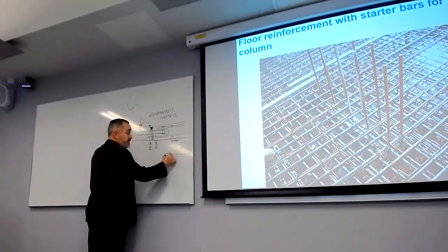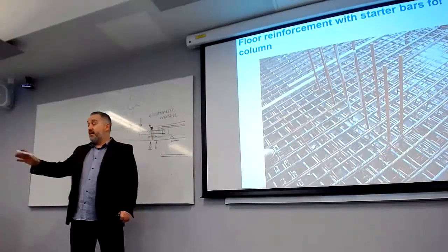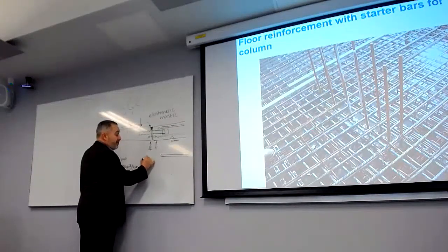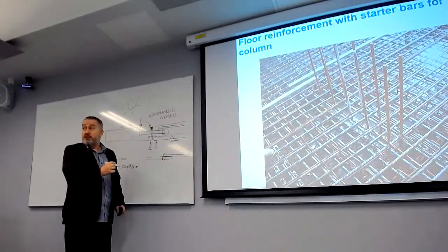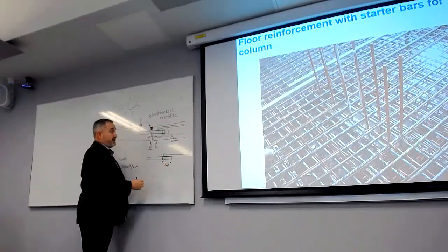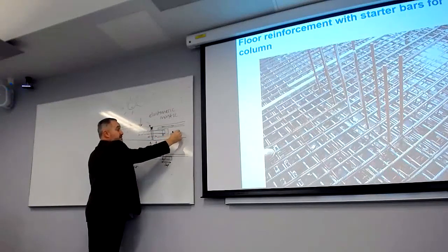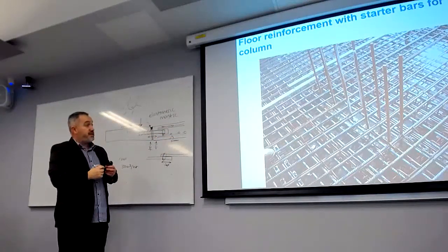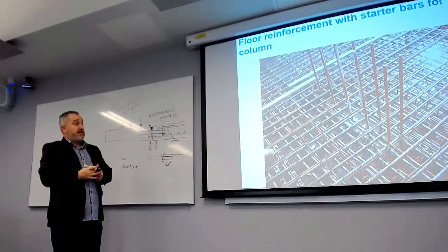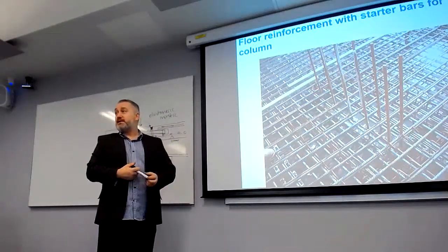you've got a steel bar, but your steel bars aren't the full length. So what you have to do is lap them together, and then you have to tie them. And then you've got rules about how far you should lap them together, and there's rules about how often you space your bars. There's a lot of detail. Seems to be a lot of detail just for a simple reinforcement and concrete.